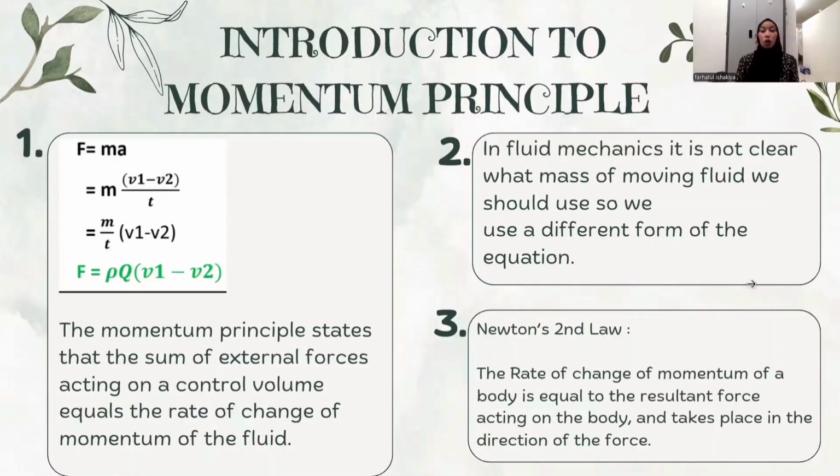Next, let's move to the momentum principle. The momentum principle is a fundamental concept in fluid mechanics. It connects the external force acting on a system to the change in momentum of the fluid. In fluid flow, we cannot isolate a specific mass, so we use a special form of the equation for continuous flow.